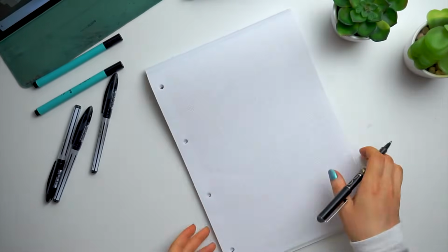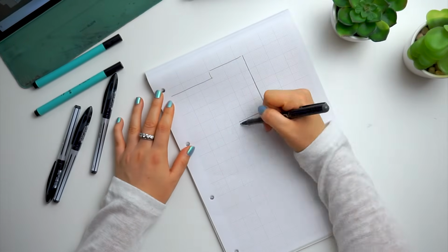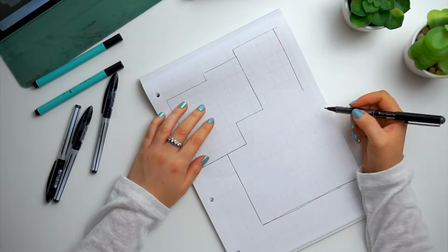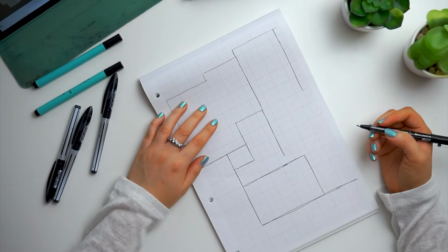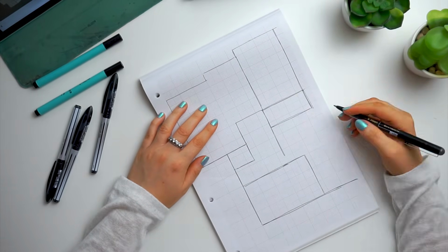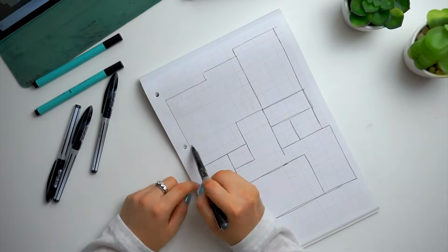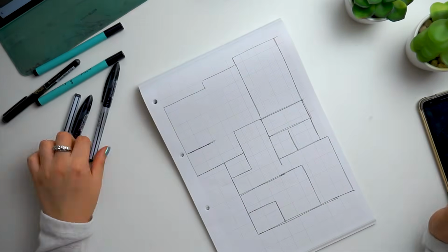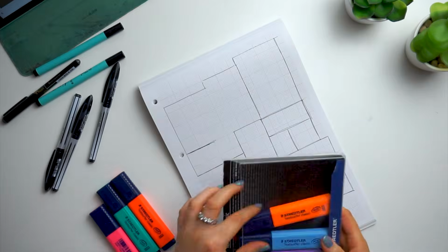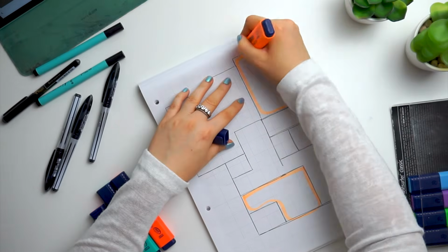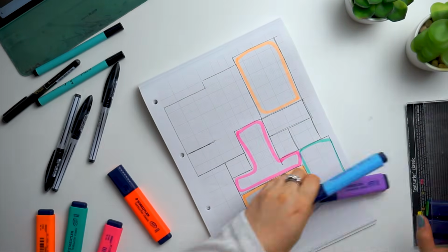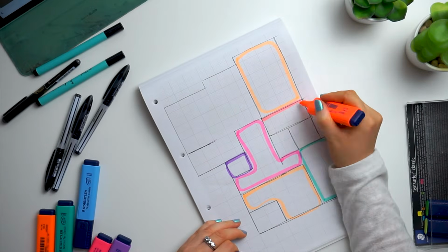I like to draw out the rough shapes of the rooms of my building, and don't worry about doing proper wall thicknesses or anything, we're just trying to sketch out the rough proportions of the space. Once that's laid out, I think about what each room's function will be and start to map them out in the form of a bubble diagram. And in all honesty, this is about my 4th zoning diagram. I like to do multiple versions of the zoning so that I can then refer to all of them and see which one works the best.